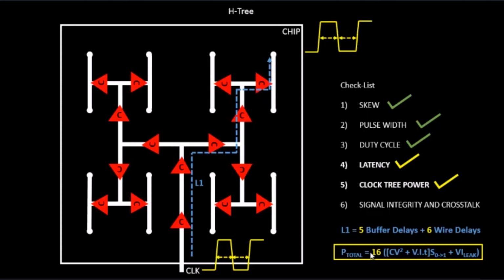So building a clock tree smartly will help a lot in the future. We will be saving power, and that is the concern of the future VLSI world. This is a point that we have to take care of, and something we need to look at, apart from timing and area. This is one aspect we have to consider whenever we build a clock tree. So this was all about the optimized clock tree for 16 clock endpoints.